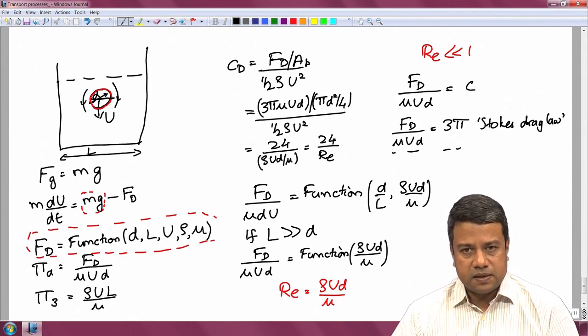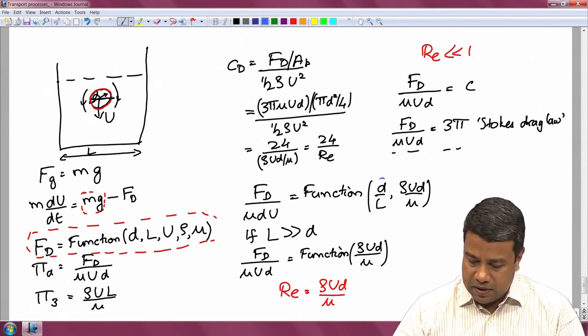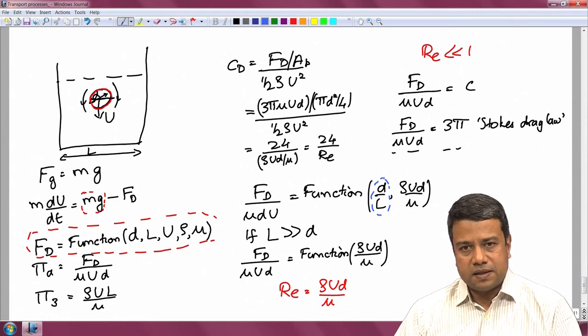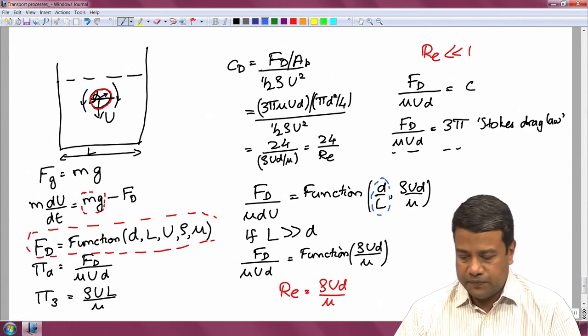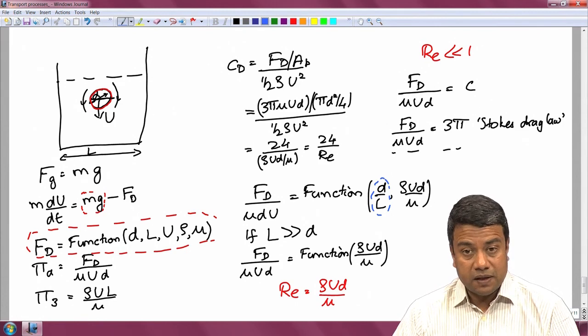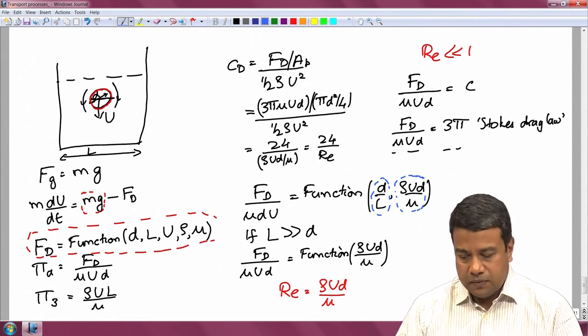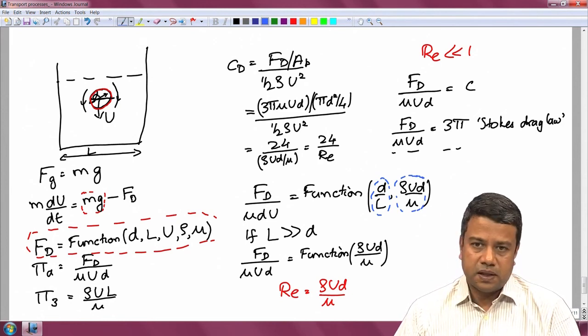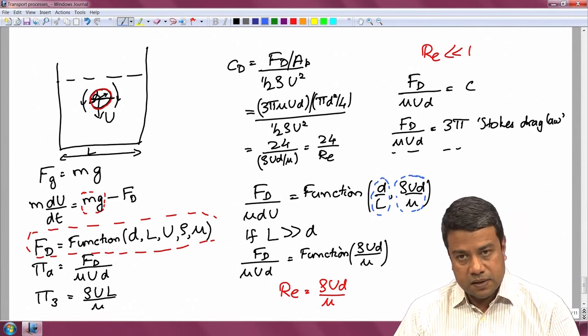We have done dimensional analysis, but a little bit more. We said that when this number is small, we can neglect this as a parametric dependence, because the tank volume is much larger than the particle size. And then we can look at different limits where the Reynolds number is large or small. When the Reynolds number is small, I said that we can neglect density altogether and we get back the Stokes drag law. When the Reynolds number is large, can we neglect viscosity altogether?